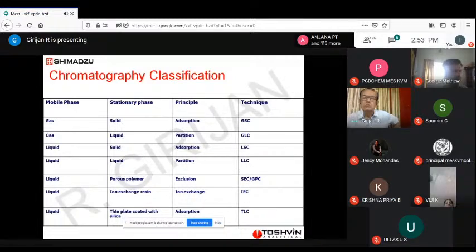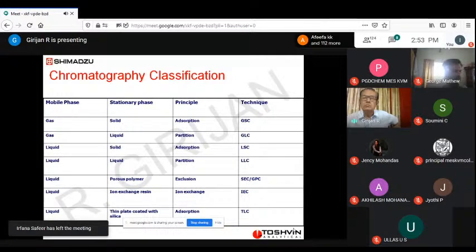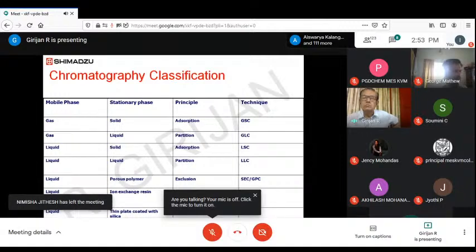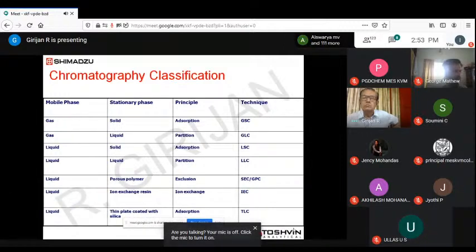There are different types of molecular weights available for a polymeric material, like number average molecular weight, Mn, weight average molecular weight, Mw, Z average molecular weight, Mz, and viscosity average molecular weight, Mv. Different molecular weights can be defined. All these, and polydispersity, the ratio of Mw by Mn, can be precisely found out using a GPC. It is a wonderful technique for characterization of polymers. In polymer chemistry, it's a widely used technique, GPC, gel permeation chromatography.